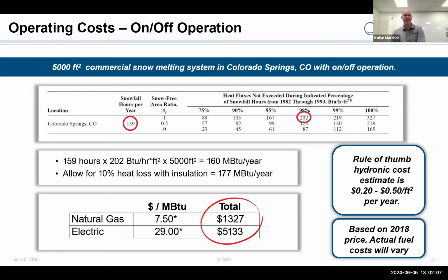The single serpentine is easier to install. It'll be faster to install. It'll take less labor to do it. The double serpentine will take a little bit more time, and it'll be a little bit higher labor cost to do that. And so now you have to weigh your pros and cons between install cost and performance variance, if that makes sense.